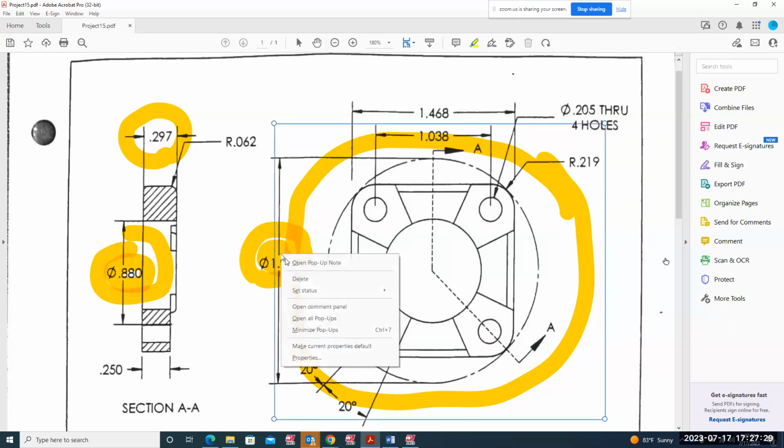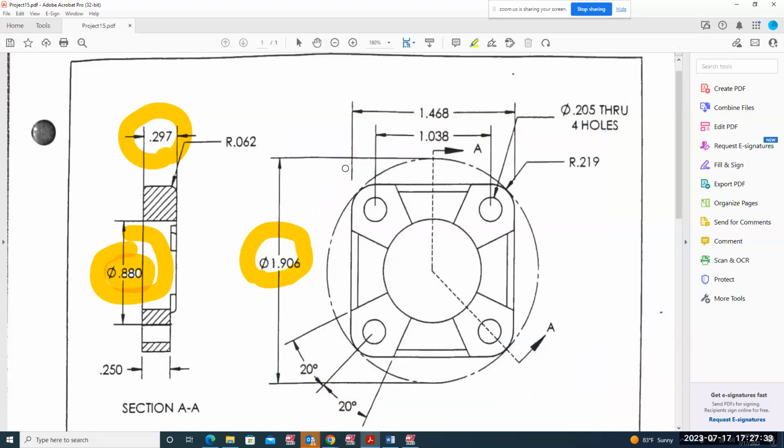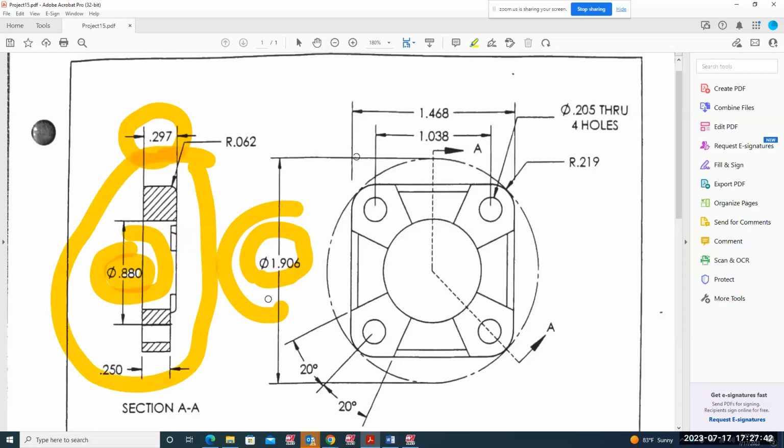The rectangle, or square, is 906. So I'm going to start drawing with the 906. No, 906 is the diameter. I don't have to draw this. I use this 906 to draw this outside, so we don't need that. We have to draw this, which is a 1.468 by 1.468 rectangle and has a corner radius of 0.219.